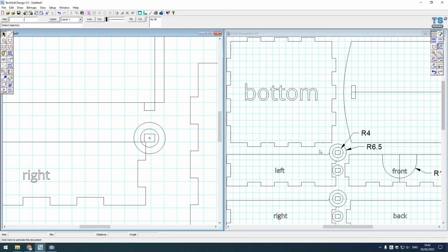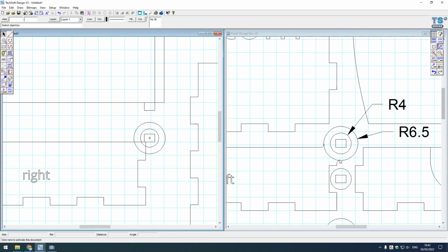And the last thing I'm going to do is just clean this up a little bit. I can see that I've got these little fillets working here, and I've also removed the lines that fit within this. So let's just come to the delete part tool. Let's trim these lines back like that. Can I get a fillet working on here? I don't think this fillet tool is going to work in this case. Let's get the fillet tool with a radius there of, let's say, 1.5 millimeters. Click on here and click on here. No, that's not going to work. No, that's not working.